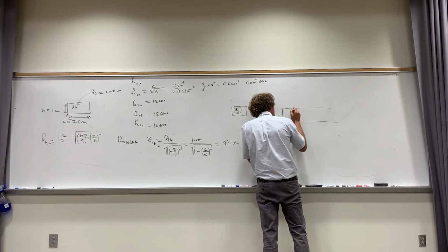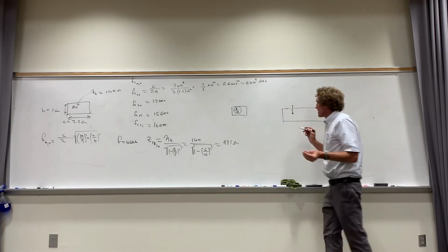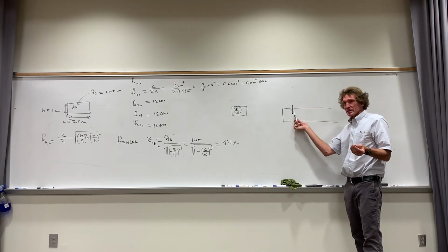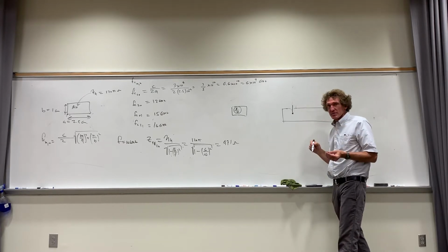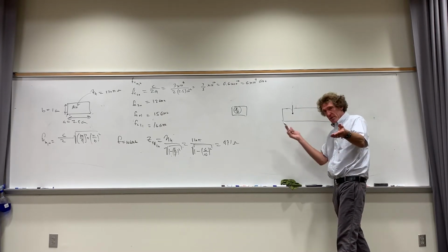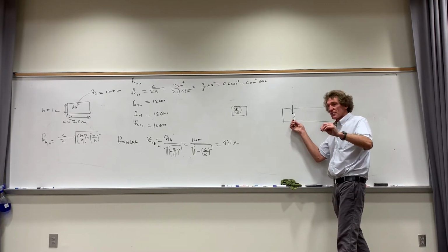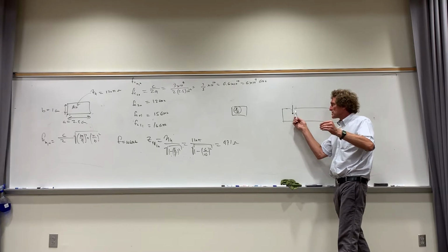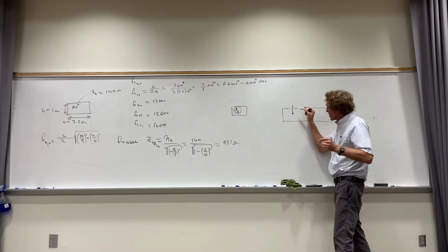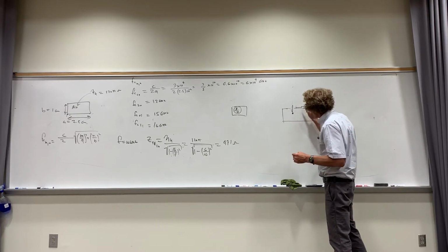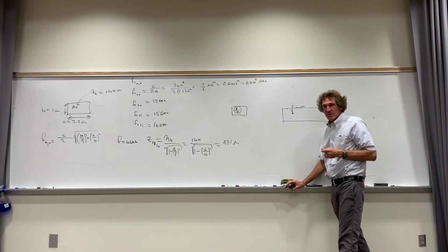They'll put a little hole here, and they'll put a short antenna down here. That antenna will energize this guide, and the impedance of this antenna with respect to the grounded surfaces there will be Z0, the operating impedance of the waveguide. You follow me on this? Because it's exciting an electric field, and the electric field would be associated with the voltage between here and here, and a current, and the current would be literally flowing down the antenna or flowing on the surface there. That would be the same ratio as the impedance right there, the 471 ohms.